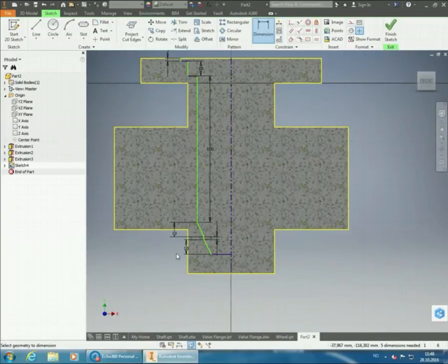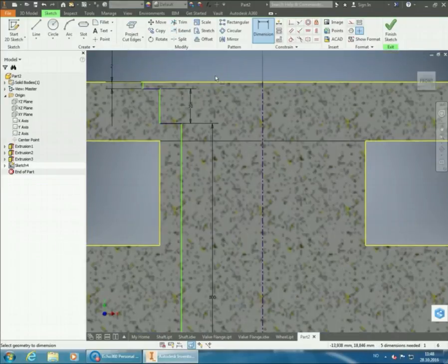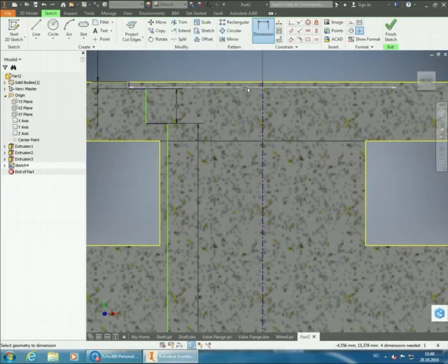Now we can start setting the diameters. So we'll start up top here. And we'll set from the first vertical line, that was 2 millimeters up there, to the center line. And it's supposed to be 78, I think. Let's see. Just double check here. 78, yes. So 78 millimeters for that first one.